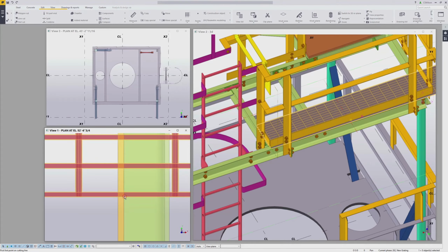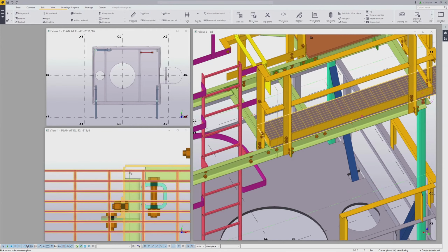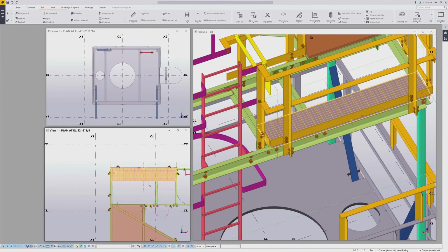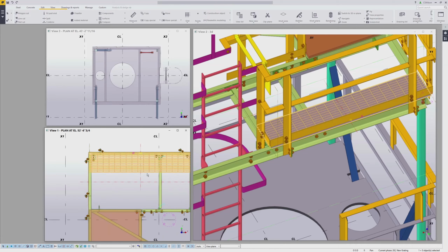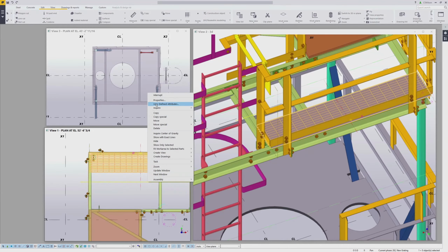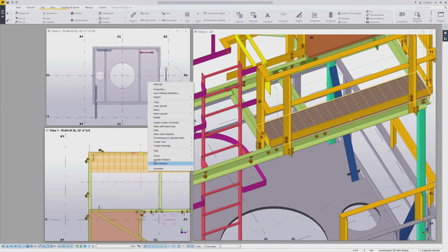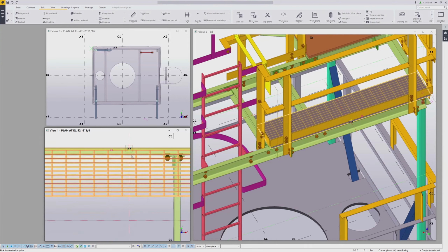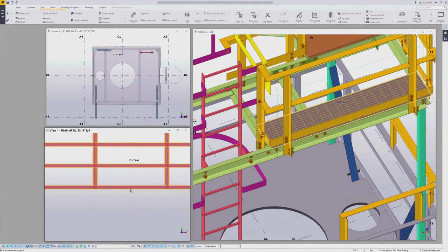Control point, we come over perpendicular 1/2 inch, we go up perpendicular, give a point, and then this time we want to cut the left side. Now I'll copy it. So we copy from this point, then we come down and give a control point here, and then we go straight down from that 1/2 inch.